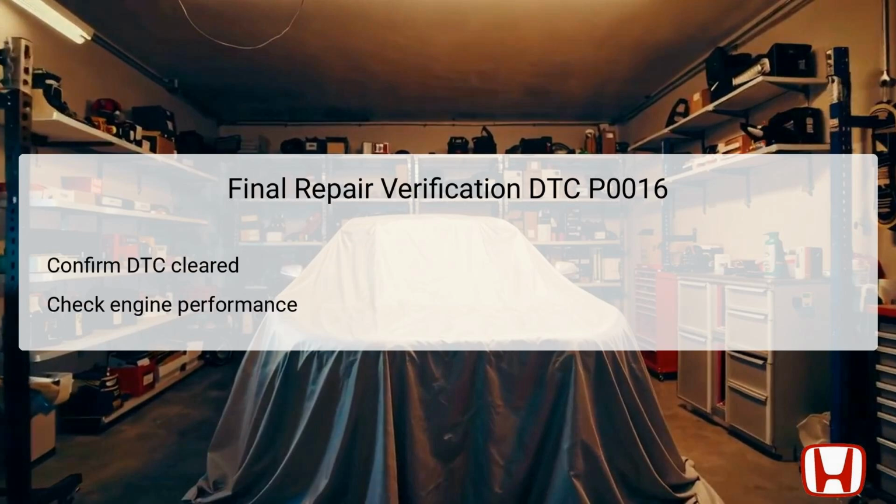After completing the troubleshooting and repair process for DTC P0016, it is essential to verify that the repairs have been successful. The first step is to confirm that the diagnostic trouble code has been cleared from the system using the Honda Diagnostic System HDS. Once confirmed, it is time to evaluate the engine's performance to ensure that it runs smoothly without any irregularities. Monitoring for any recurring symptoms such as stumbling, stalling, or poor fuel economy helps verify that the issue has been fully resolved.